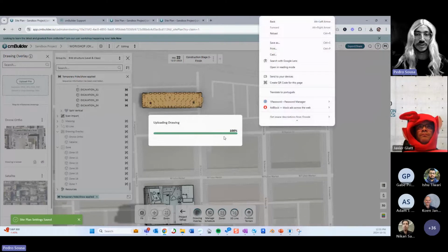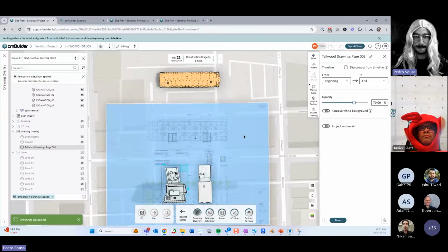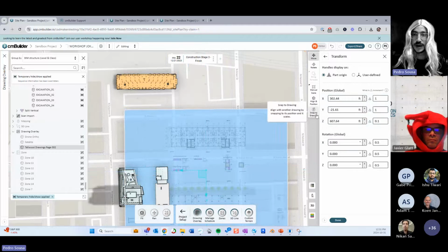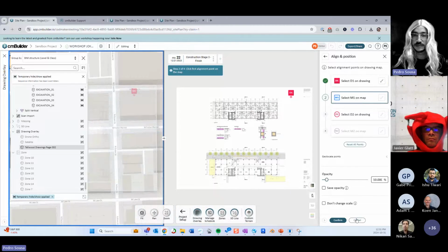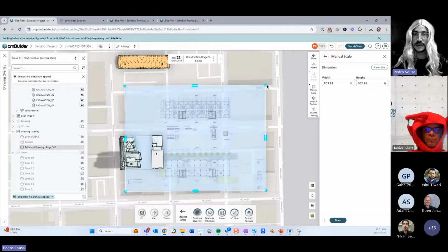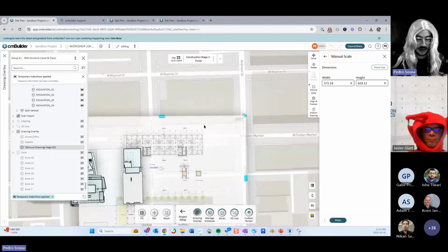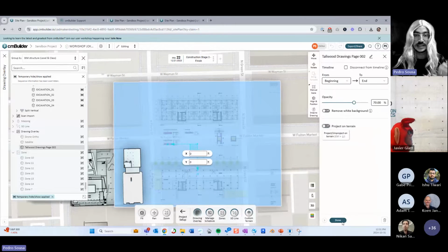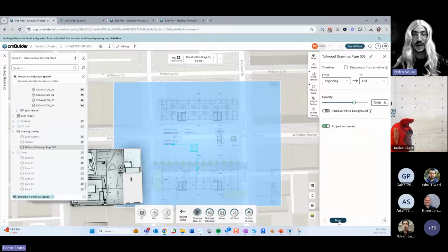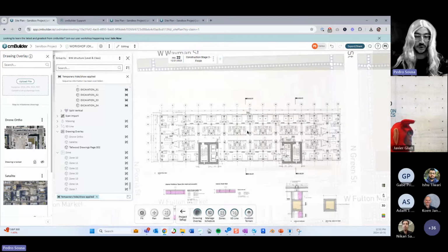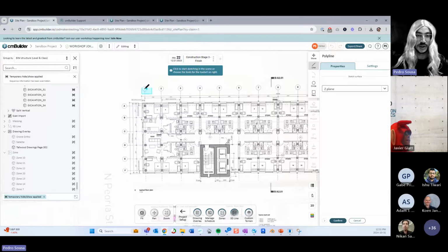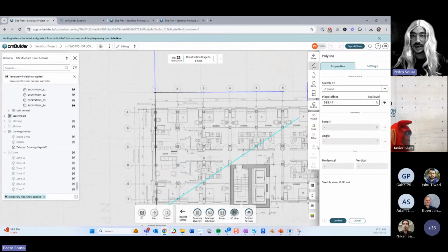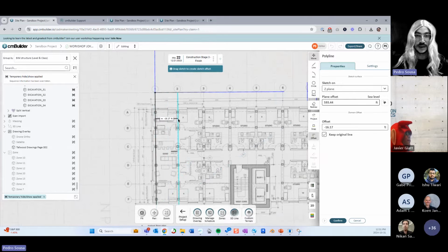And I can place this drawing somewhere. Let's say here, right? And I'm just going to reduce the size of it a little bit. So in one of our recent workshops, I showed how you can create these grid lines using the 3D lines tool, right? So basically it will be the same idea. So you create a template using a 3D line tool, and you can draw where your grid lines are and things like this. You can use the offset to place them on the right spot.